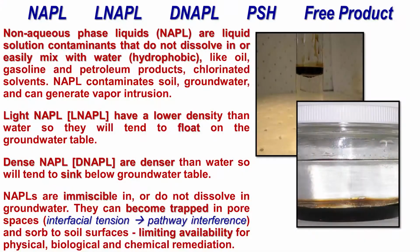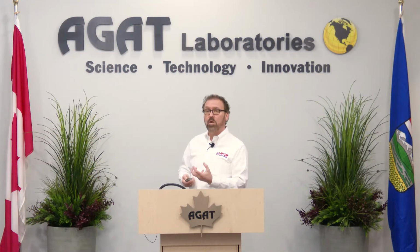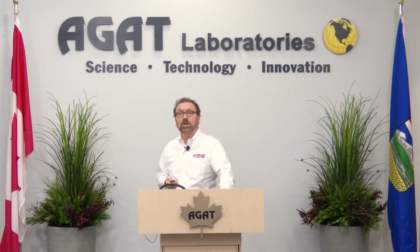So when you have this contact taking place, as you can see between these free product floating and sinking layers, there's interfacial tension also in play. The surface tension of water is 73 dynes, while the surface tension of most contaminants, whether petroleum hydrocarbons or chlorinated solvents, is in the low 20s. So a big difference. And that can affect movement of these or your intentional movement or interaction with these when you're treating soils and groundwater.